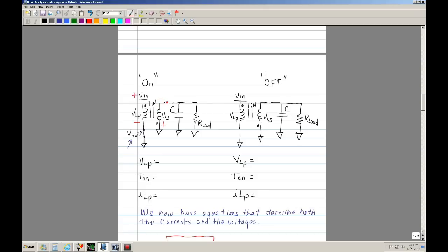Now remember there's a diode here. So if this negative is going to the anode, it turns off the diode. So basically you have a diode that's off, so you can model it as an open. During this time at steady state, the voltage that the load is provided is by this capacitor.